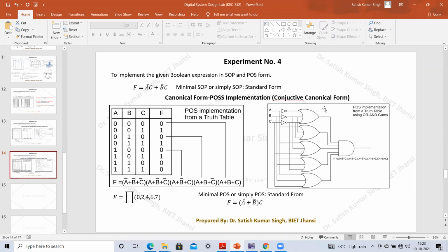So that's why I need a total of 10 OR gates when we are having just 2-input OR gates. That's why I have chosen 3 ICs, because each IC has just 4 gates, and I need 10 AND gates and 4 OR gates. We actually require a total of 10 OR gates, and therefore I have chosen 3 ICs. Now you try to do this implementation.